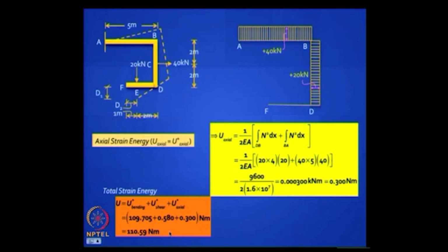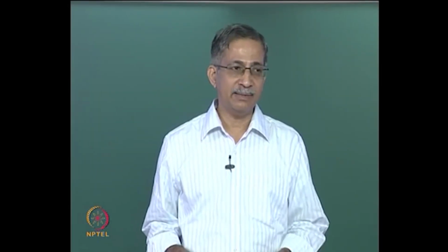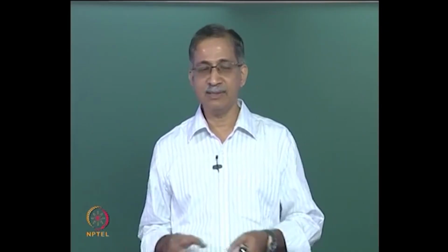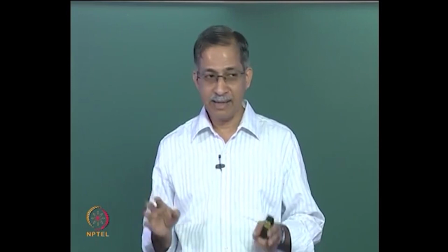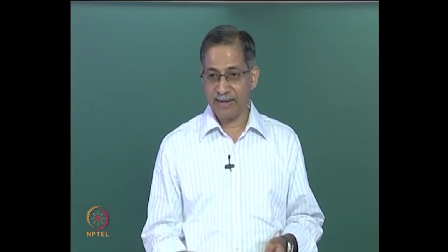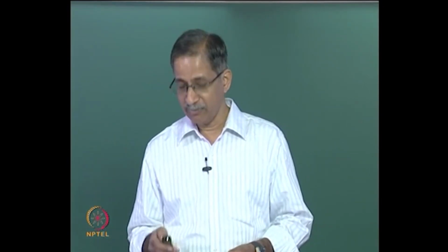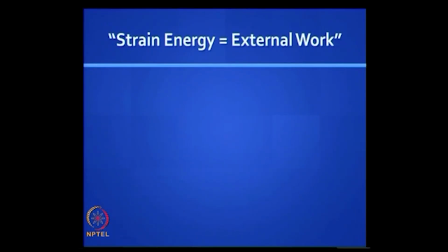So you can clearly see that you can ignore shear deformations and axial deformations. It is like assuming that the shear rigidity is infinite and the axial rigidity is infinite, and that is the reason why this assumption that we frequently make in structural analysis when we deal with frames is justified. But there are exceptions, and if you want to be accurate you can include those effects as well. In matrix methods we will do problems where we can do this more exactly.